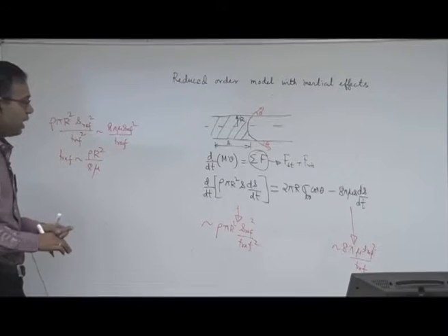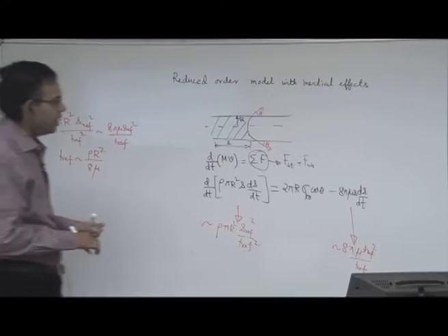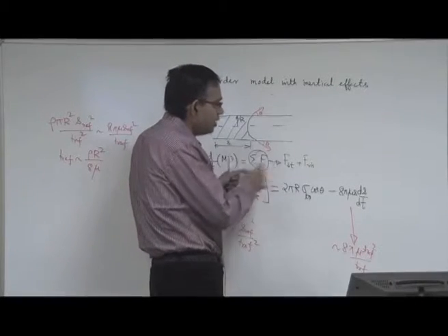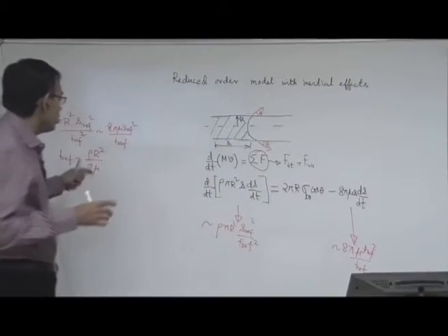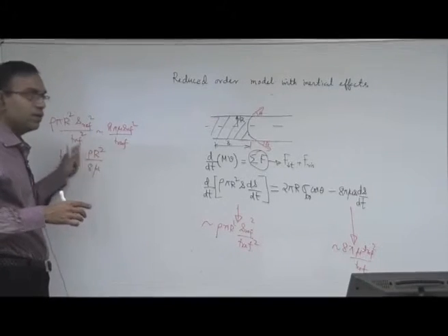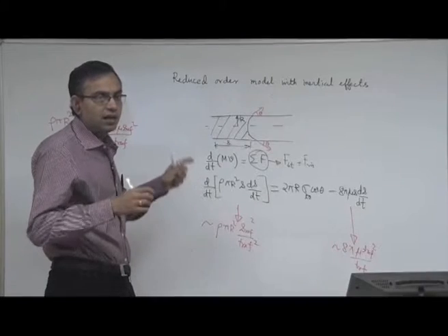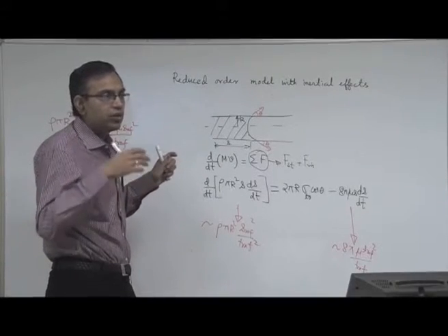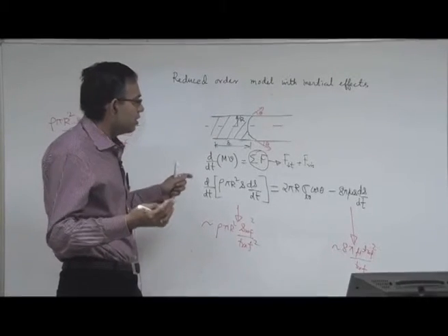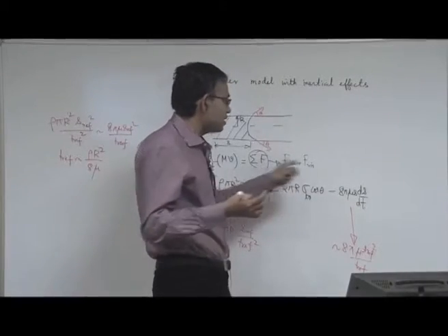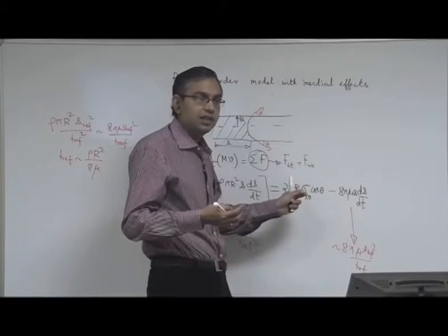Here we are not bothered so much about the scaling of different forces considering the inertial effects. We will simply use this for non-dimensionalizing the governing equations, and it will not differ notionally so much whether we do it on the basis of inertia versus viscous balance or inertia versus surface tension balance.